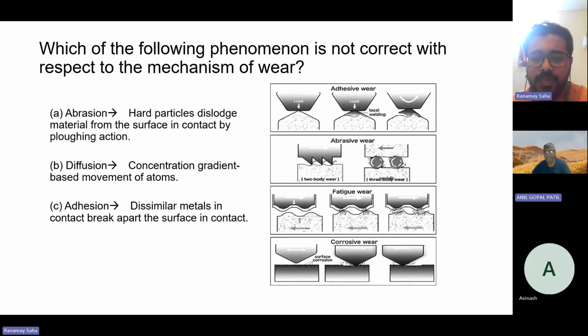Corrosive wear is encountered when the surface is exposed to open air. There can be oxidation on the surface of a part, and owing to that oxidation, the surface gets weakened and its durability gets affected. When that surface comes in contact with another surface, the affected, oxidized surface may corrode. So this kind of wear is called corrosive wear.